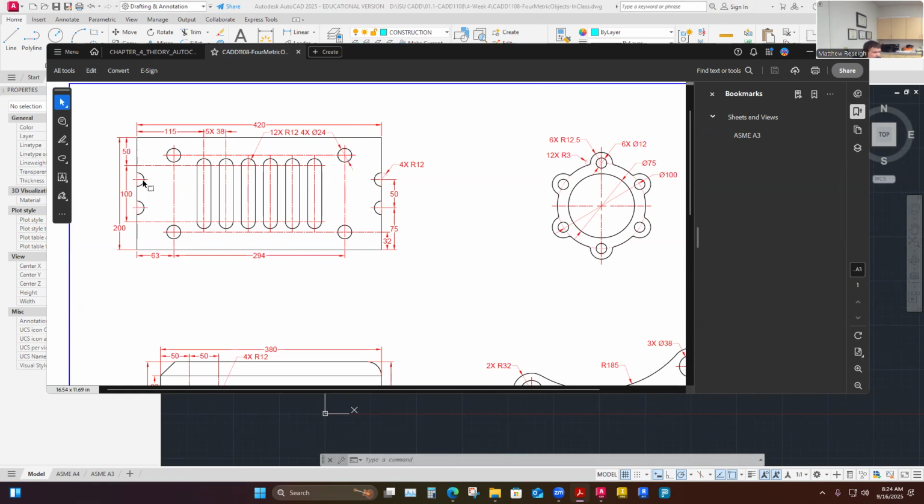Not totally necessary. What I am looking at is maybe these features here. And right here, it looks like they come off 75 and then 50. They're actually dimensioned on this side. I'll probably put them in on this left side over here first. I could say 2 places here, I could say 2 times, just because there are no dimensions for that over here. It's understood that those are in alignment.